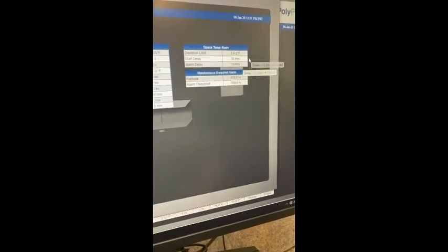Say the unit was disabled or went into unoccupied because they left the window open or whatever, then there's a 30-minute delay for the alarm. If the system's just been running and has been active for over those 30 minutes, then it's a 15-minute alarm. So if the space temperature is outside the range after 15 minutes, it's going to throw an alarm. That's pretty fast.